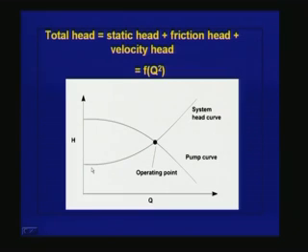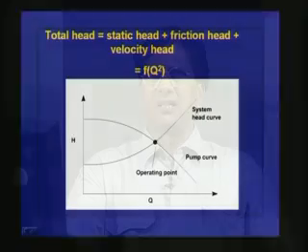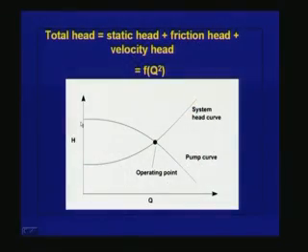that is shown here. And the other curve that I am showing in this figure is the pump curve. The pump curve is given by the manufacturer. After designing the pump and fabricating the pump, one can conduct a pump test. There are standard procedures available for conducting the pump test, and this head developed by the pump, which is equal to the delivery pressure minus the suction pressure, one can easily find out during the pump test by installing a pressure gauge on the delivery side and a pressure gauge on the suction side.